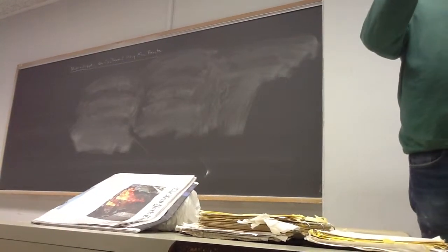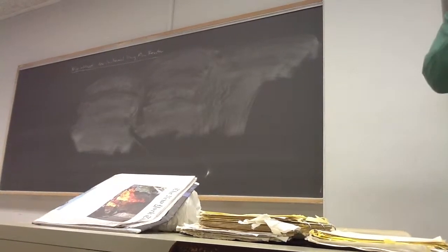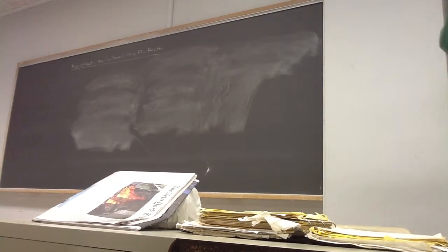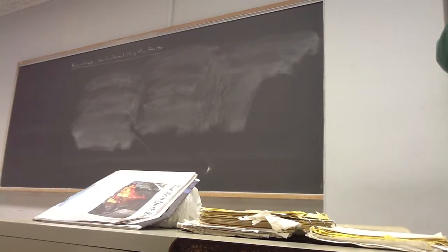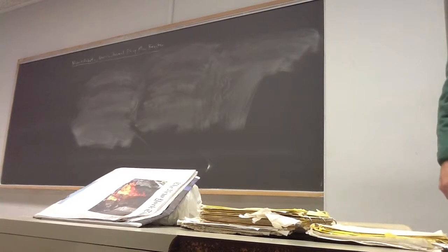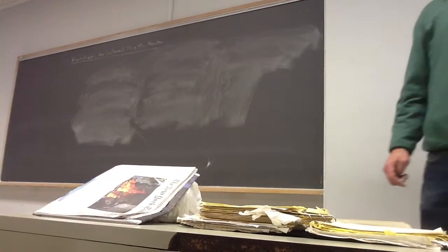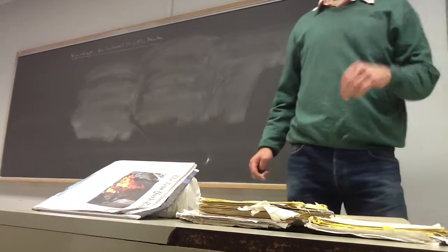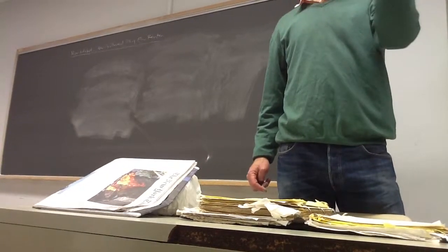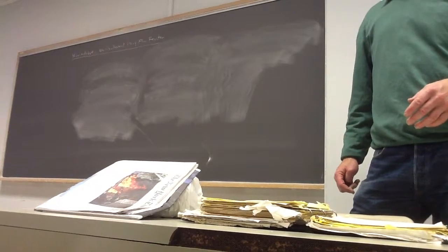What happens is when the catalyst gets too hot, then the metal atoms start to move and they start to agglomerate. So you have a lot less of this interface. But the other thing that can happen is your catalyst support, the alumina or whatever it's made of, has lots of little sharp points and edges where the metal could sit. And when it gets too hot, then sometimes they can sinter. They can sort of singe. And then again, they no longer have catalytic activity. So that's some of the potential mechanisms by which, when the reactor gets too hot, you kill off catalyst.